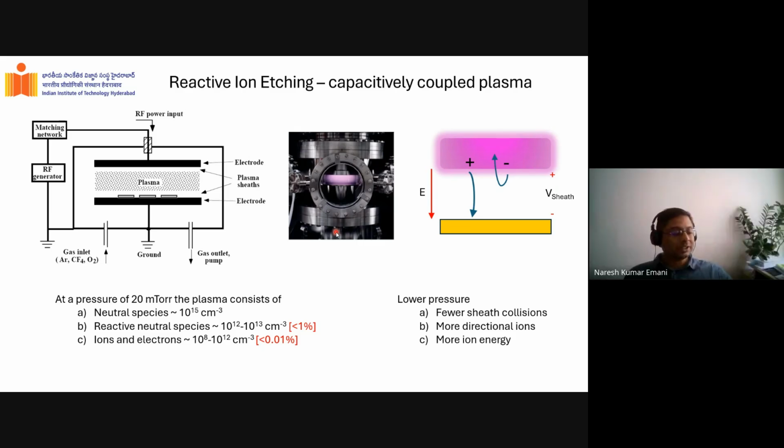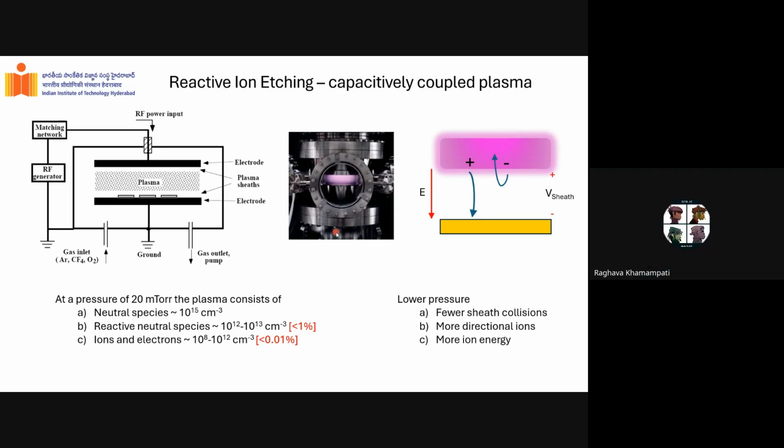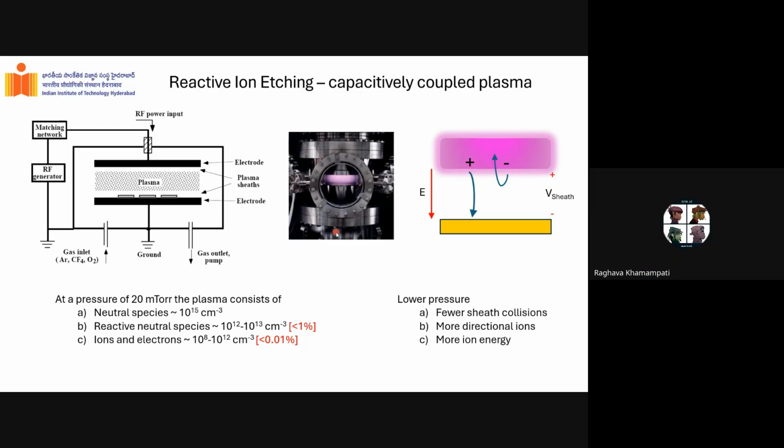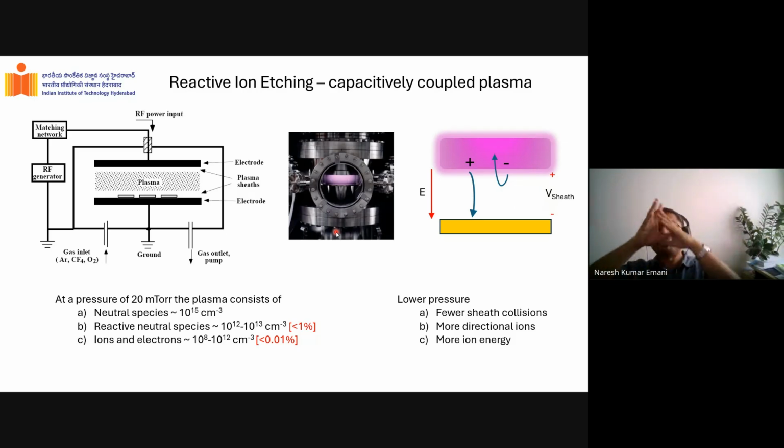Yeah. Dry is better. But what will be the difference if we are using this and that? Wet will have something called stiction. Basically, when you try to have the liquid evaporate in wet etching, you will actually have the liquid in between the cantilever and, let's say, the substrate, right? And as it dries, it tries to make the cantilever collapse onto the surface. Okay. So there are some techniques called critical point drying, which you have to use to make sure that, carefully and without collapsing, you release these structures. But in dry etching, you don't have to suffer with all that. Make sense? Sir, but etch rate will still be less. Etch rate will be a problem, but yeah, it can be done.